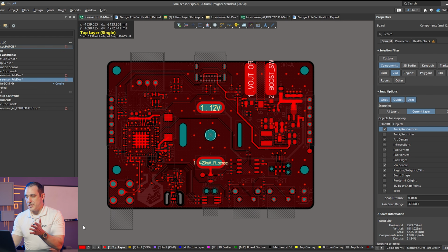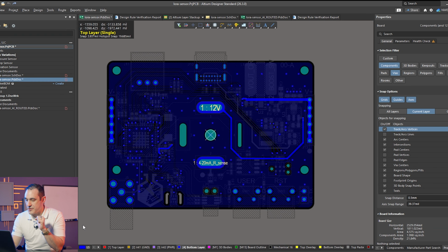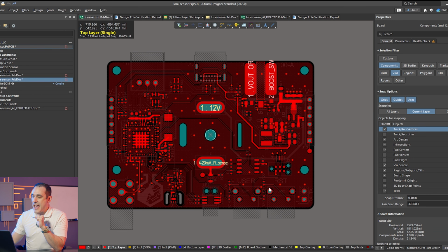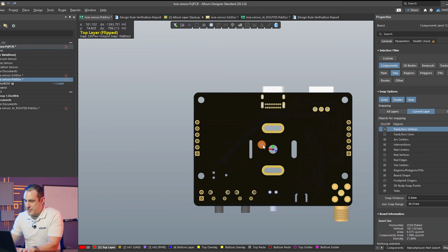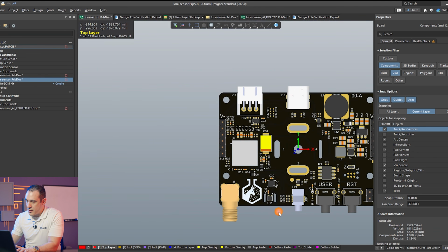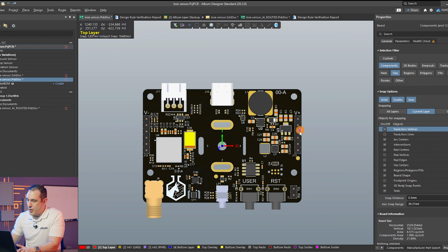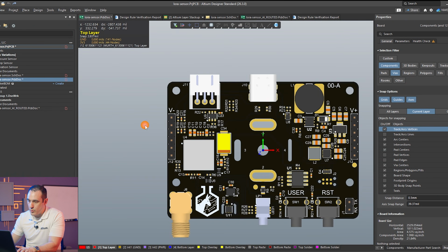So here we have the human-designed PCB layout on screen. This is a 4-layer board, and it is in the signal, ground, power, signal layer stack. And you can see here in 3D that the topside placement has all of the components, and then we have some through-hole connectors along the top and bottom side. We also have a couple of pin headers here for our battery input and for our ground.